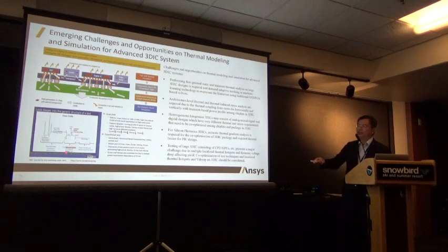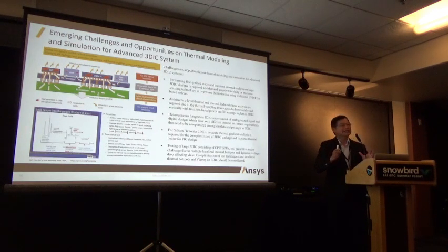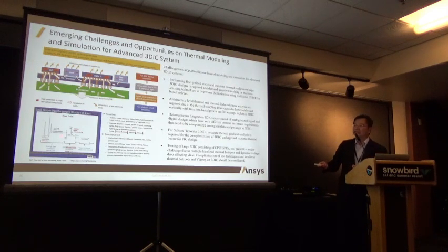The other application, with Teledyne Advanced Test, is testing large-scale 3D IC systems. The new challenge is that the thermal hotspot during speed testing will move from one location to another within 5 milliseconds. So you have to predict where the transient temperature hotspot is. Otherwise, your control of the chuck temperature will be imbalanced, and then you will have a yield loss.